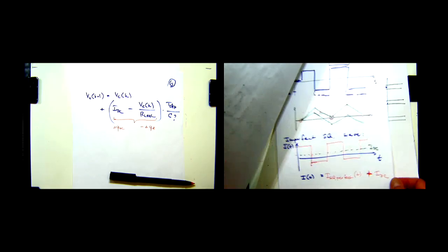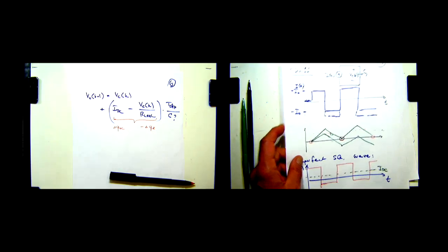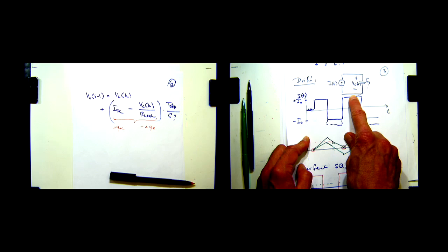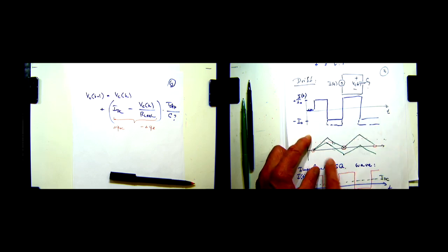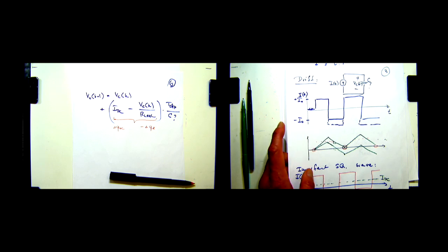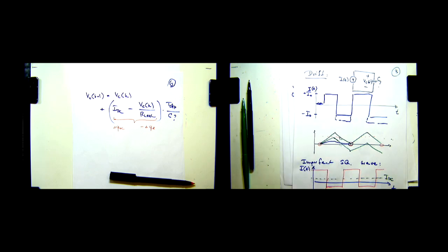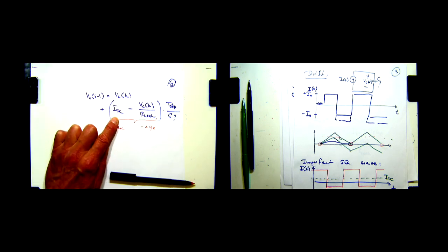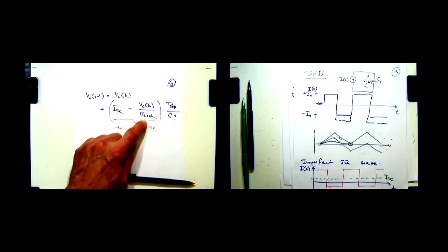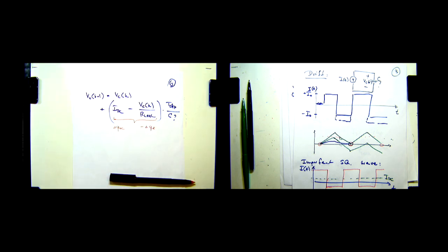Where do I have this? I must have this somewhere. Yeah. If we were to put a really large resistor here in parallel to the capacitor, instead of getting the voltage that increases here, it would basically not increase almost at all, right? So we couldn't detect anything with that circuit anymore. So in practice, it's a bit of a trade-off. First we make this IDC small, and then afterwards you choose a leak resistor that just makes it work. So you're going to build this in the lab.